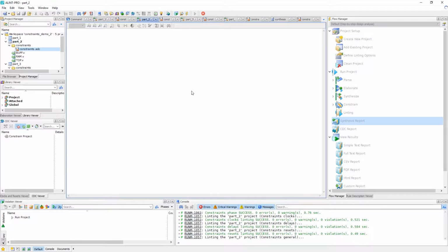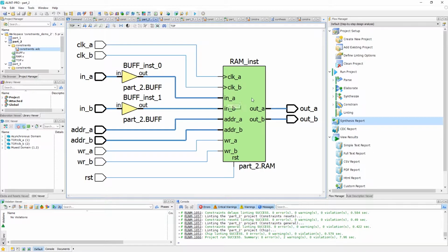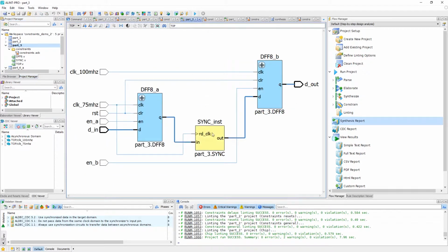The tool no longer recognizes our unimplemented module as a black box, and now properly displays the module with correct clocks, inputs, and asynchronous clear here on the side. Moving on to our next example, I'll now show a library function that can be used on a more general type of logic, as this project utilizes the libsynchronizer function.